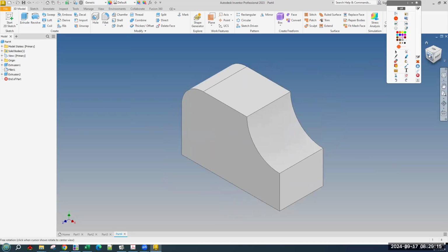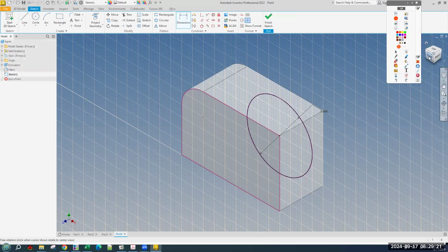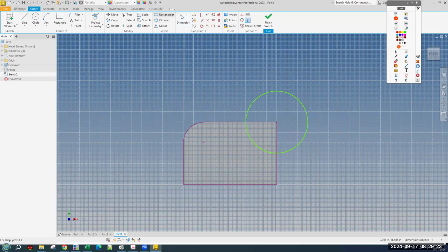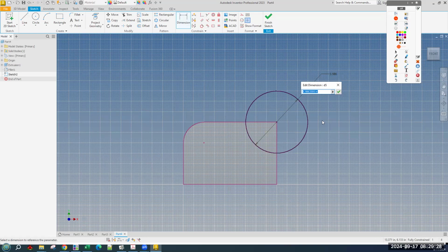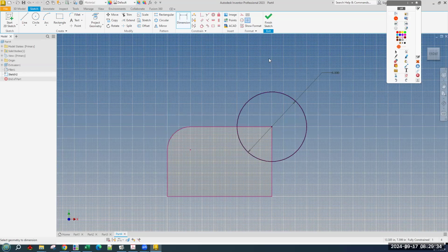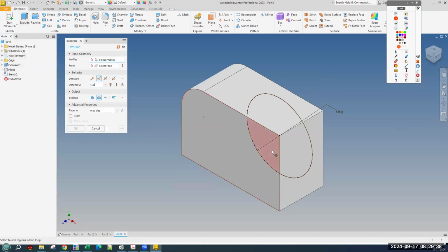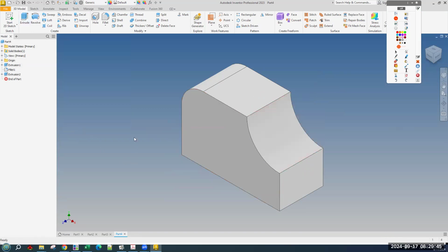What's up? Oh, have we not dimensioned circles yet? Awesome. All right, so for a circle, all you need to do is click on the edge on the circle. First click on the circle, second click up here. Dimension is 6. Okay, finish sketch, extrude, choose what we want to cut, switch it to cut, and go through all. And hit OK.